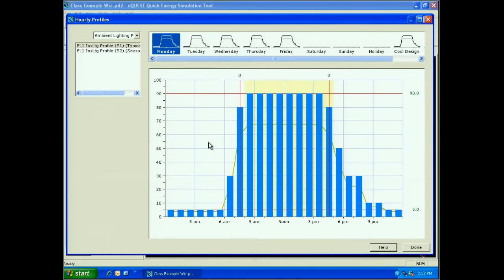It comes up to a maximum during the day and tails off again in the evening. And again, you can adjust the minimum and maximum, just like we showed before. You can also change the starting point and ending point at the end of the day by putting plus or minus the number of hours that you want to shift in there.